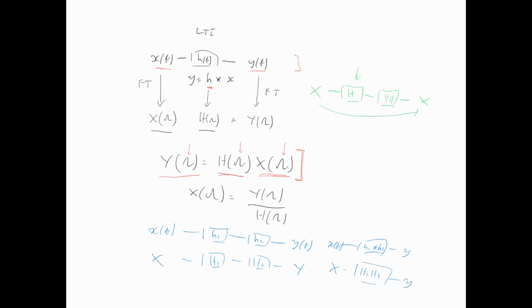We mentioned before that convolution means smoothing, and undoing smoothing should be difficult. So how do we see this in this representation here? Well, if my room absorbs certain sounds, that is, if I get destructive interference, that means that at some frequencies, H of omega is going to be close to 0. And 1 on 0 is certainly not defined. So if my room perfectly absorbed a particular frequency, meaning if I transmitted a 1 kHz signal in my room, I won't actually hear anything. This of course depends on where the sound comes from and where I'm listening from, etc.